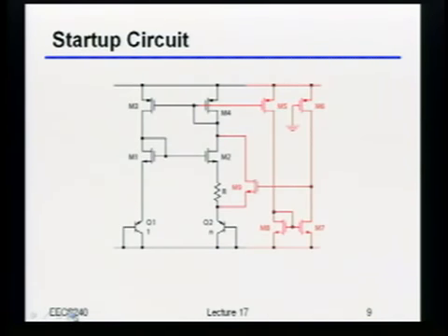So let's walk through one example for how something like this might happen. Let's say that this is our PTAT circuit right here, and for whatever reason it started out with zero current, which essentially means that that VGS is 0, and that therefore this thing right here is sitting up at VDD. Right? Because that's the only way I could have zero current in this circuit.